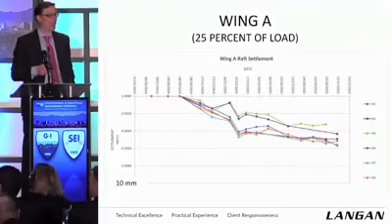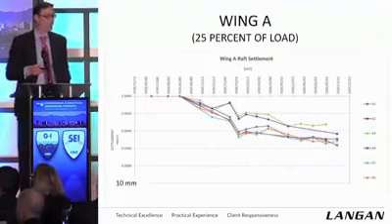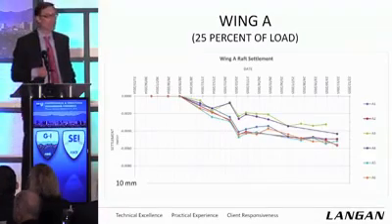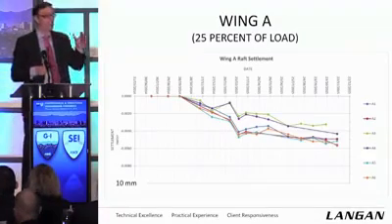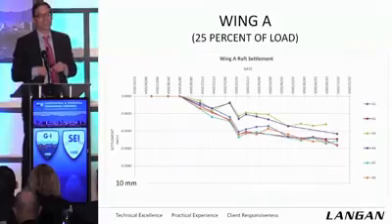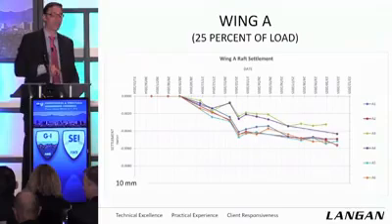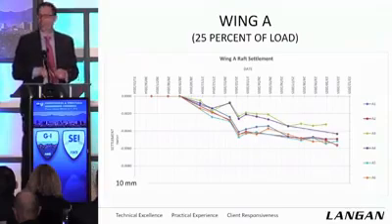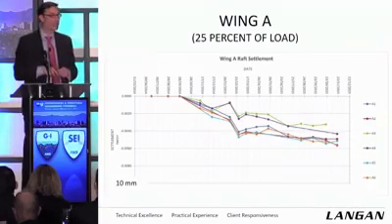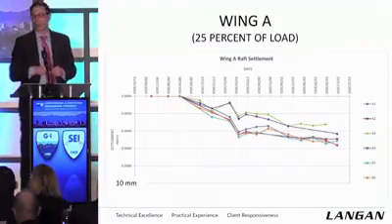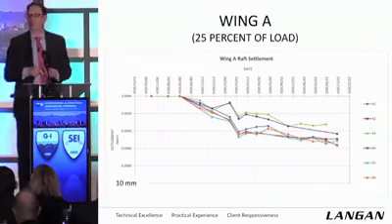And wing A is again about 5 to 6 millimeters, and wings B and C look about the same. I think it's going to take off a little bit as the stress increases at that lower weaker layer, the poorly constituted sandstone. I think it's going to increase some, but overall we've probably overpredicted settlement by a factor of 2 is my guess.